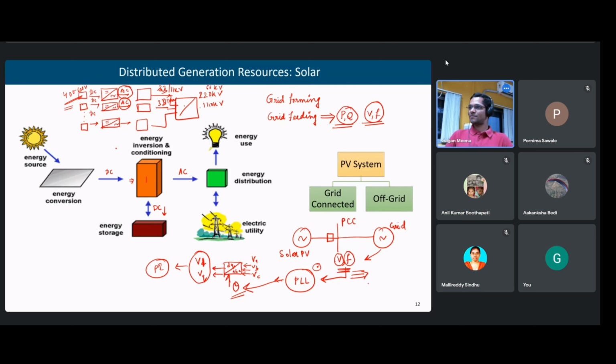Because if the microgrid is islanded, we need some generator, we can say a slack bus, which can provide that constant voltage and frequency. But their control is not designed in that way, so they cannot provide that constant frequency and voltage. They will just keep on pushing power P and Q. They will not care if the voltage is rising. Because right now, what happens in the distribution system, this is one of the problems, because we have these grid feeding